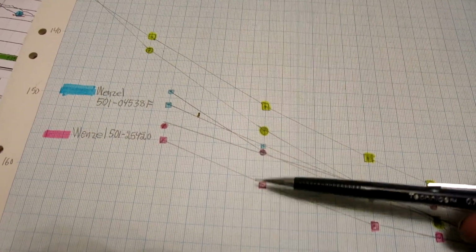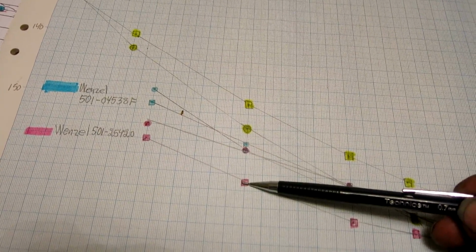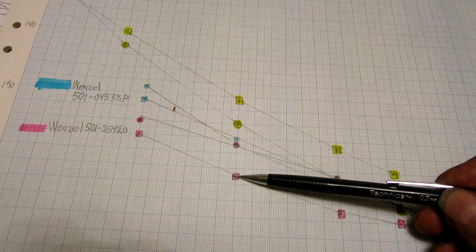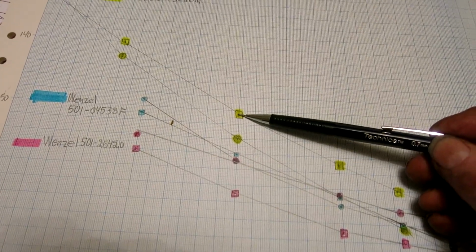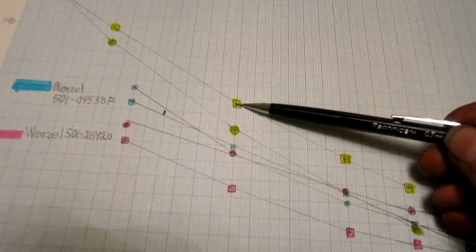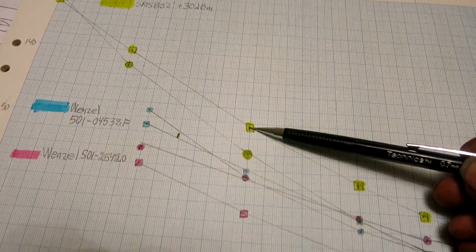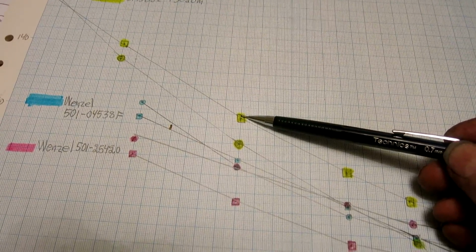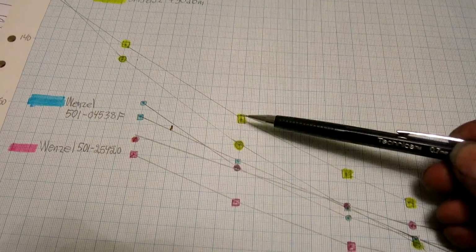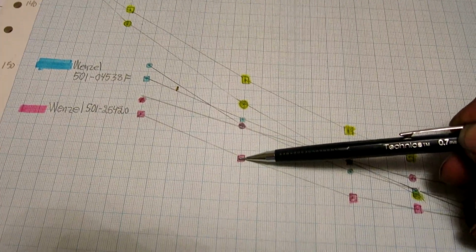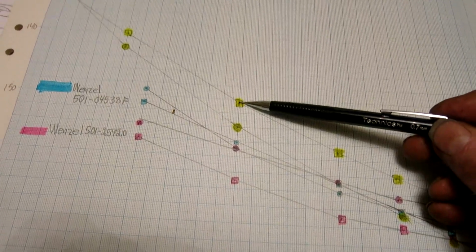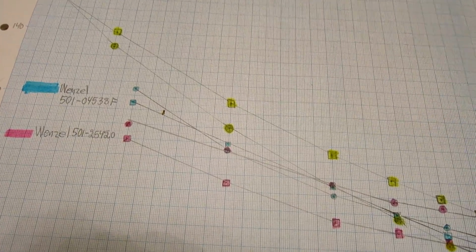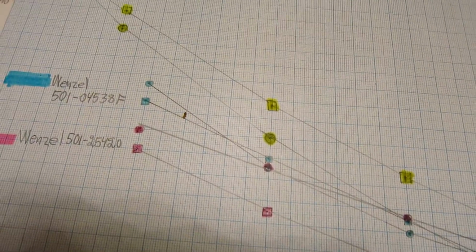It means I can use this very good oscillator in terms of amplitude noise to send a signal into my own homemade oscillator, which I can use as an amplifier to see how much noise it adds depending on the power level, and I can also inject the signal from the good Wenzel into different stages of that amplifier to see where the noise is added and perhaps understand the mechanism.